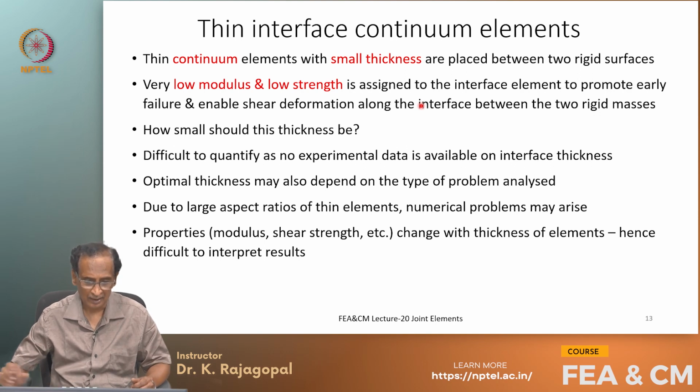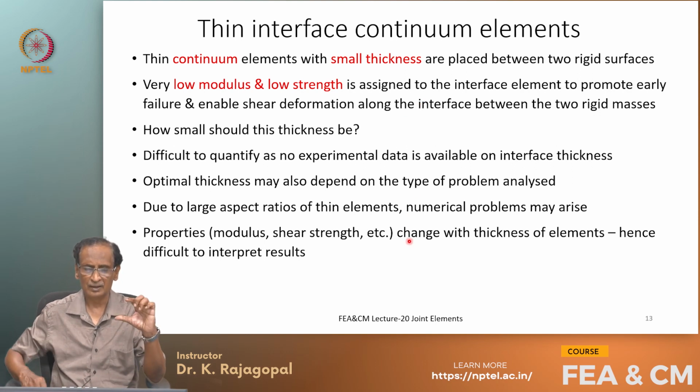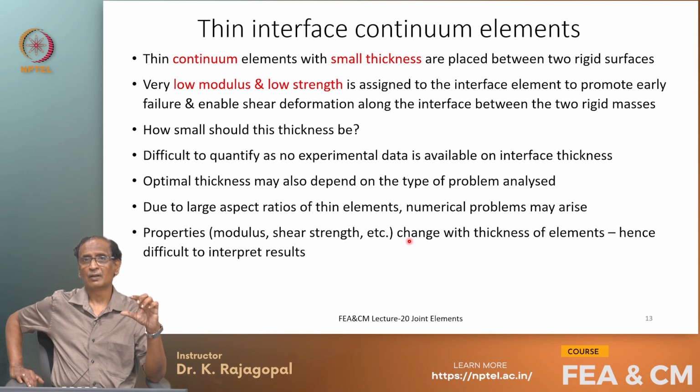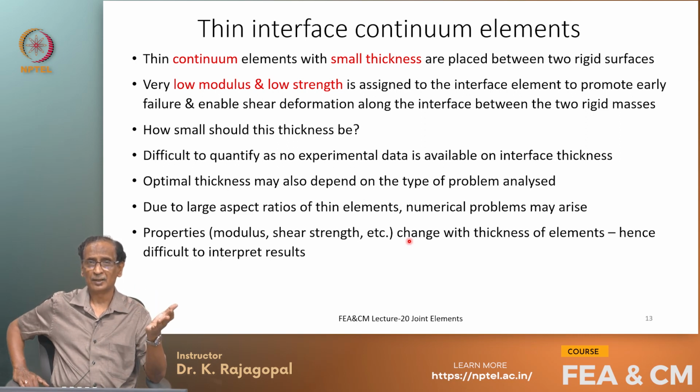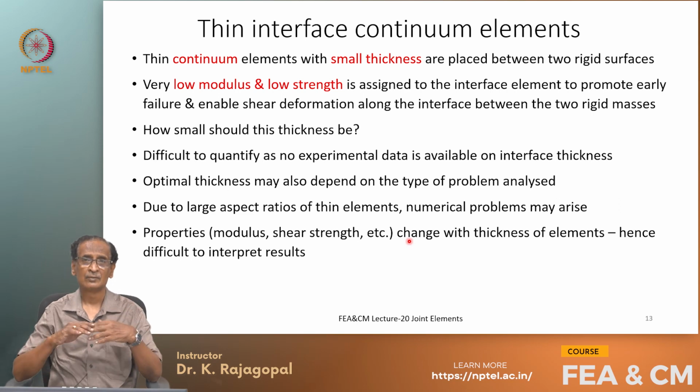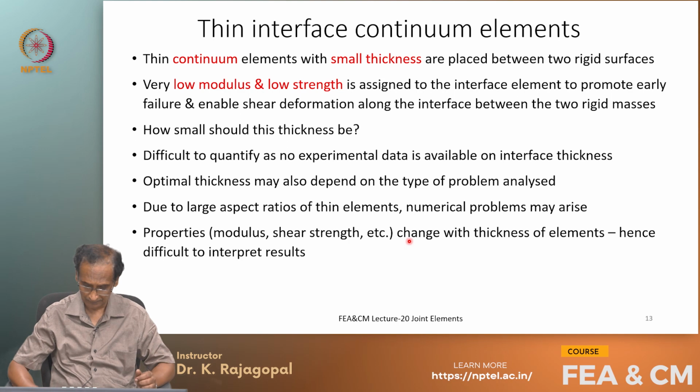And the other problem is that with the different thicknesses that you use for the interface, your properties might change. The modulus that you use, the shear strength properties that you use, you may have to calibrate a little bit so that you can get some reasonable results.